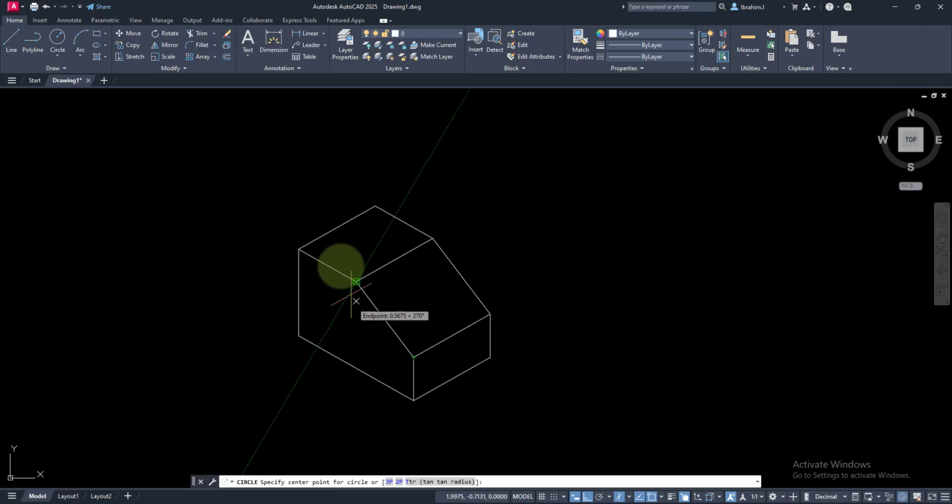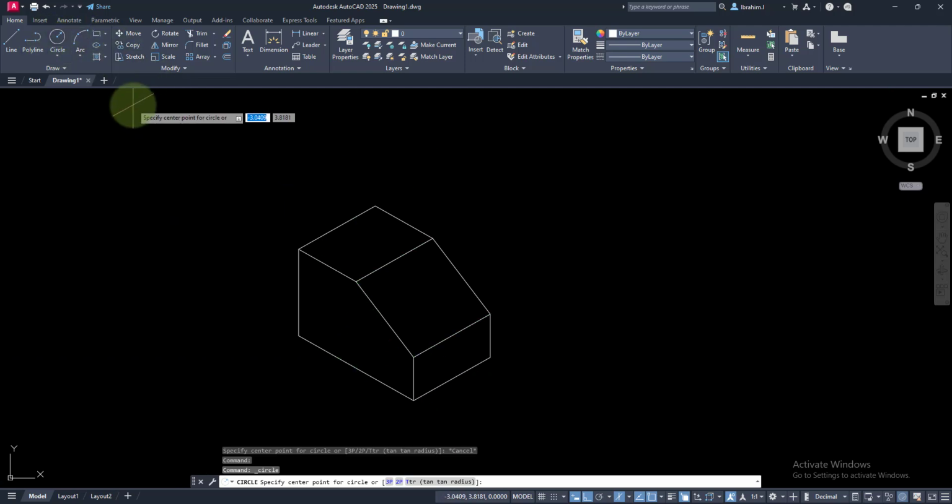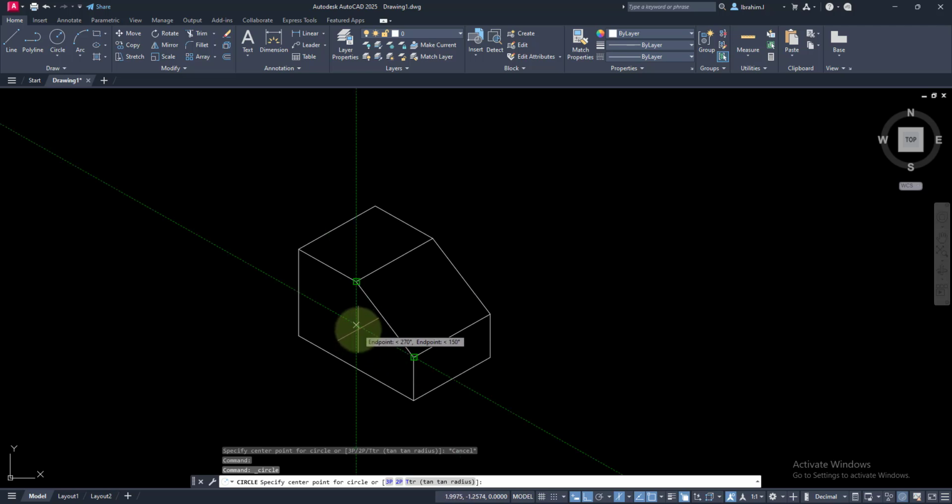Now go back to this design. I'll use my same circle center radius. I'll be giving radius of 0.5. Try to do that using this. You see that we have an error. I'll track from here and I'll track from here. Whenever they meet, that's where I want to put my circle, right?